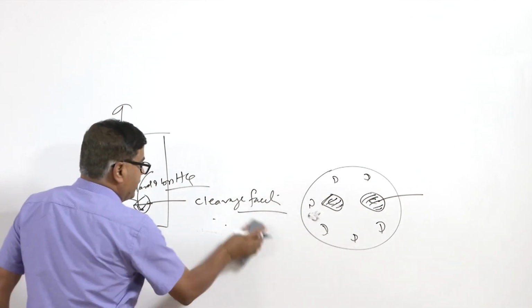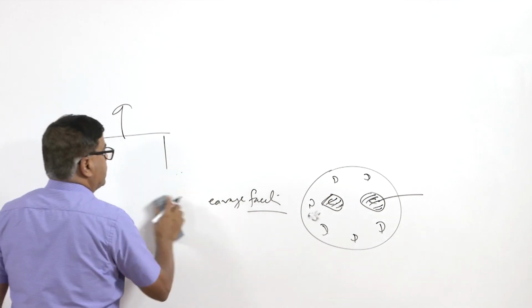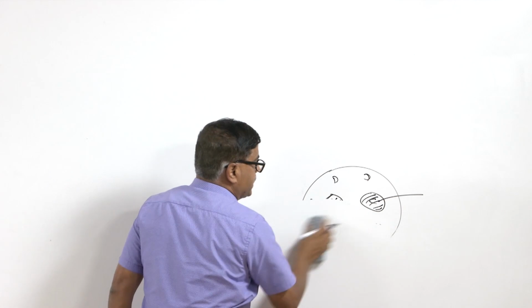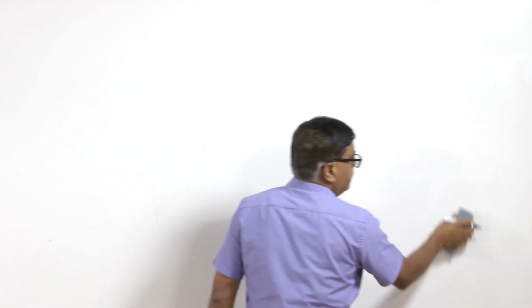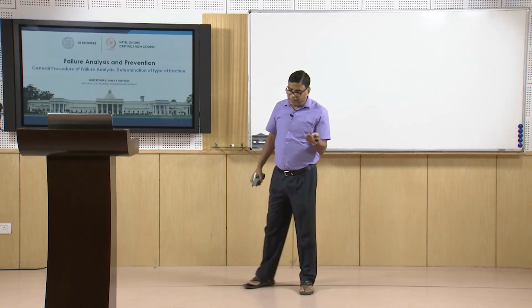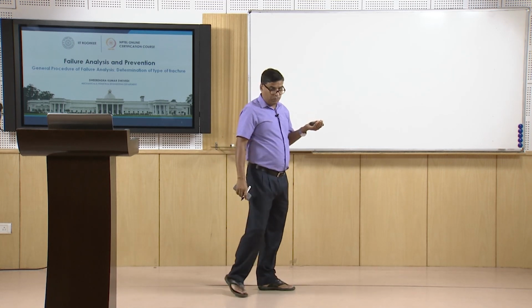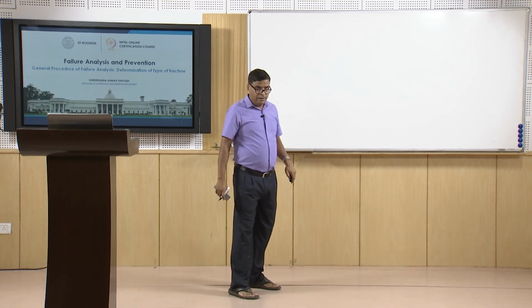So, metal systems having hard and brittle carbide particles, or silicon carbide in an aluminum matrix, or coarse polyhedral primary silicon particles in an aluminum silicon matrix, will fracture either by cleavage facets, or the particles will get pulled out under the influence of the external loading.